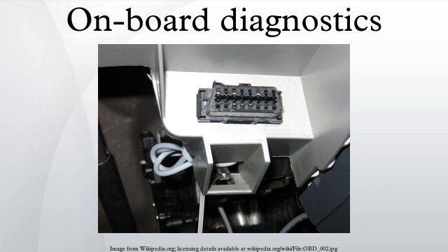Modes of operation. Here is a basic introduction to the OBD communication protocol according to ISO 15031. Mode $1 is used to identify what powertrain information is available to the scan tool. Mode $2 displays freeze frame data. Mode $3 lists the emission-related confirmed diagnostic trouble codes stored. It displays exact numeric, 4-digit codes identifying the faults. Mode $4 is used to clear emission-related diagnostic information.